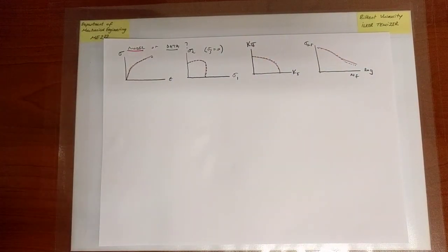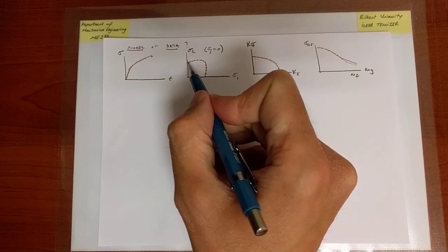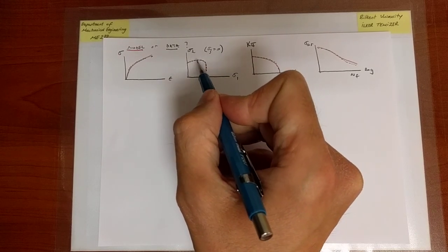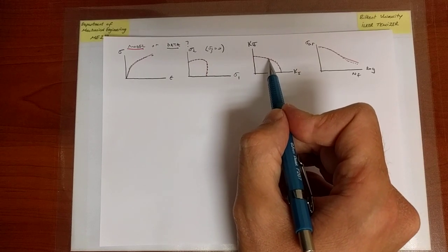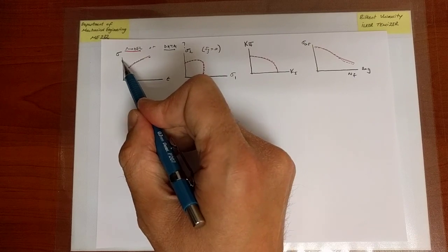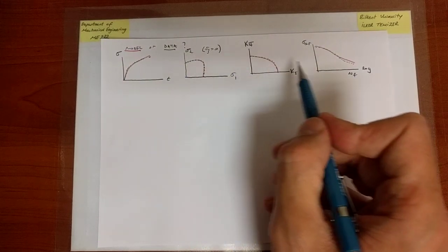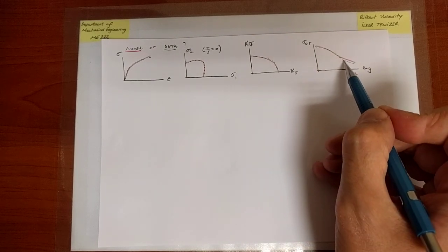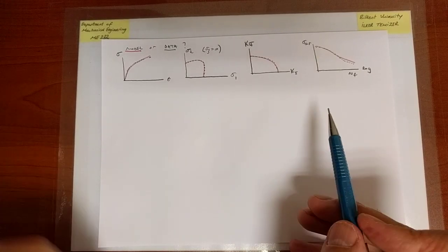So in either case, what we can observe is that if the number of points is sufficiently dense and they are nicely distributed, not too much scattered, then I can directly make use of the data points, and for a given strain, find the corresponding stress, or determine whether a combination of stresses is going to lead to failure. Or in this case, you give me the number of cycles desired, then I can find the corresponding stress,